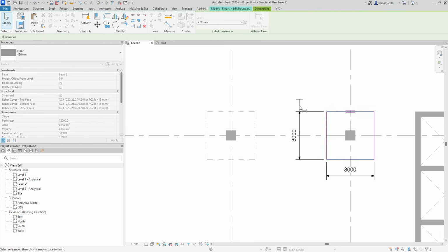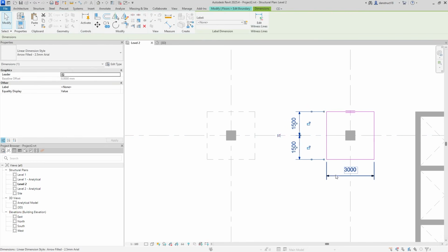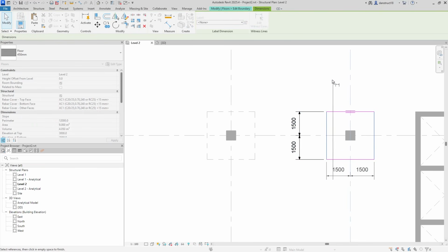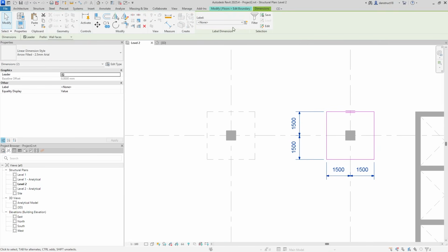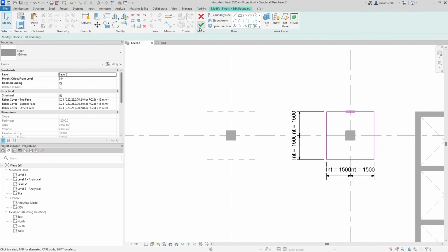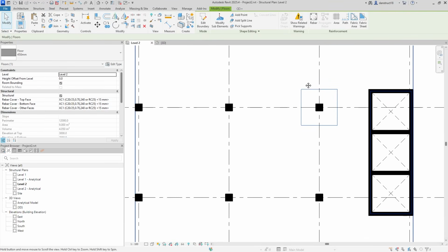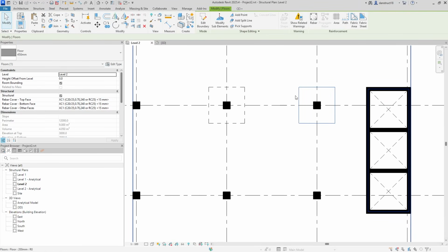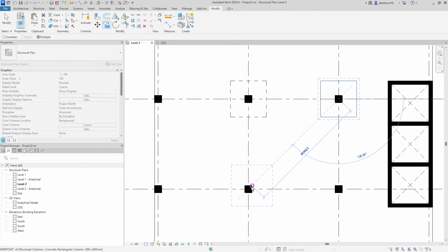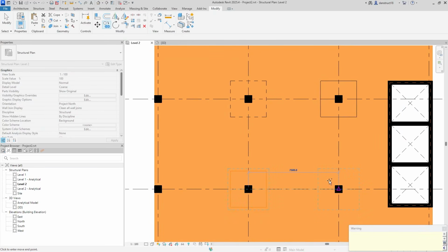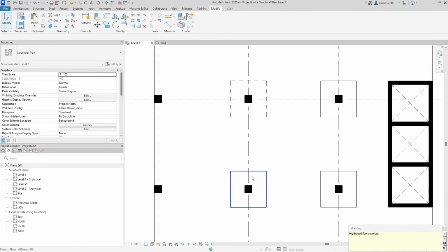So you have to go ahead and set it again. So I'll select this, edit witness line, add a dimension here, select this and add this reference rather here. You also have to select the two as well and just go over here and set it back to int. Alright, good. Now this may take a lot of time, but it's actually rewarding in the end, especially when you have a larger project and a lot of updates to make. So I'll select this one here. I'm just going to click on copy, then I'll paste one here and another one here, press escape.